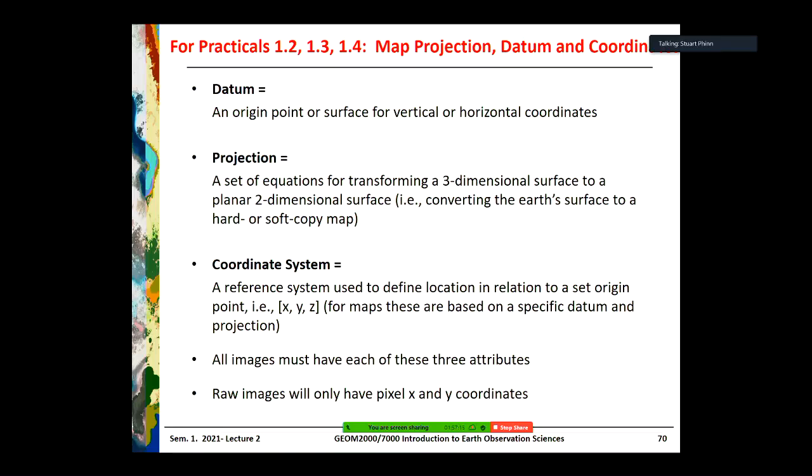When you take a measurement, like with the GPS on your phone or an actual position measurement system, you'll get a coordinate, and that coordinate will have been measured using a certain datum and projection. What happens particularly with geospatial data sets is they're collected with different datums and projections, and then people go, I'm going to put them together.